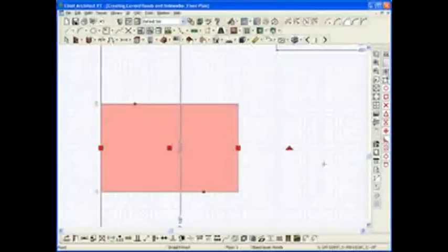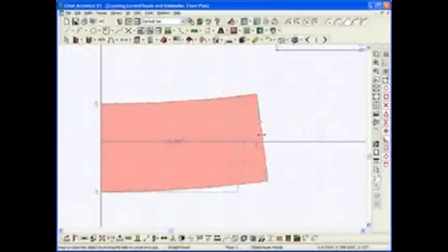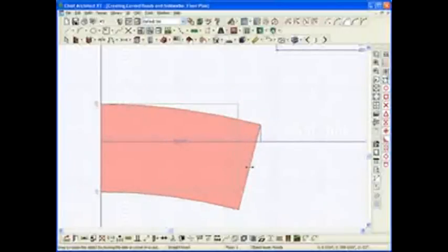But if I click on this road, notice those three handles that I get right here. They're the same three handles that I got for that CAD polyline that I drew on the floor plan before. So again, I could grab this end handle and bend this road. Again, I'm going to hold my Alt key down, and you'll see that I could bend that. Now let's turn the angles back off here. See how I can bend that line that's in the center of that road.